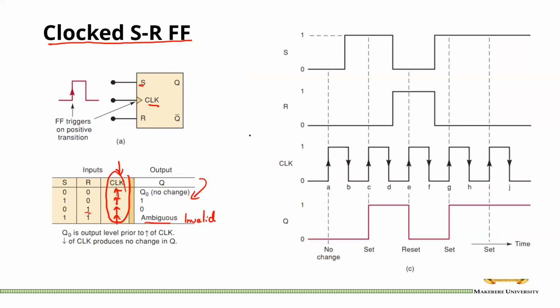Imagine when you set your clock, immediately you change the inputs. That would be similar to you driving out of your gate, and even while you are still driving over the gate, somebody is closing it, it might hit your car. So in other words, you give a bit of a lag for the active clock transition to actually perform its functionality. That is really the importance of that.